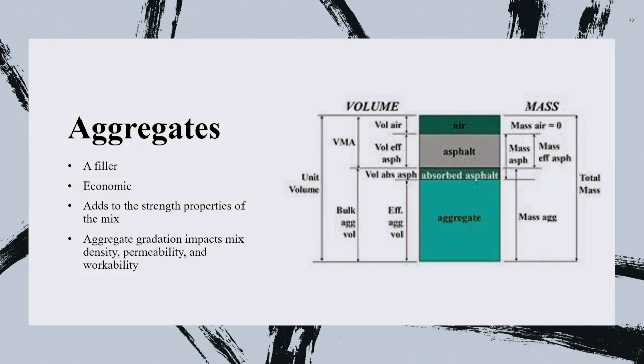Now, in our asphalt, do you remember this phase diagram from soil mechanics or from asphalt, or even the ACI mix design for concrete? They call this a phase or block diagram. All the mix designs, whether for concrete, are about how to proportion the constituents. What are the constituents of concrete? You have cement and water, that is the hydrated cement or the glue, and then you have the filler, which is coarse aggregate and fine aggregate.